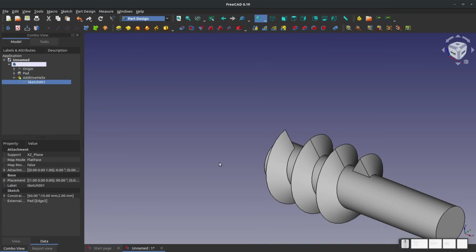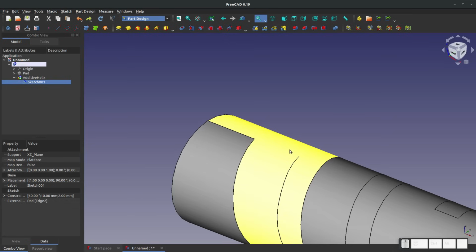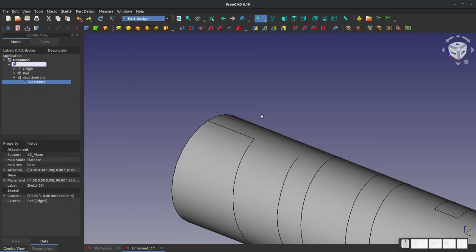So this is something that occurs in all CAD platforms that I know of. This is called zero thickness. When you have a result like this, right, I hit Control Z to go back to where we were. We're saying that we have a sketch that we're moving on, and we don't know if we need to add material or not right where these things intersect, right? Right at that point, is there material or not? So by adding a little bit of extra material inside of this part, we have resolved that error.